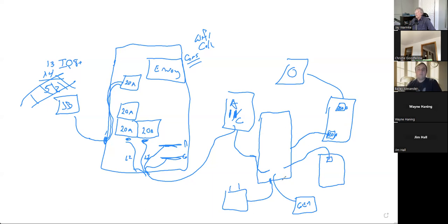And oh, there's one other thing that I have, and that's from here, I've got a second disconnect, and it's referred to as the rapid shutdown initiator. It's basically a DC disconnect. The reason you need to have that, and it's got to be located out here next to the AC disconnect by the meter, the reason we have that is, let's see what happens when the grid goes down.